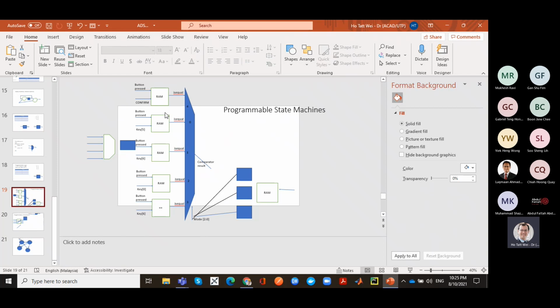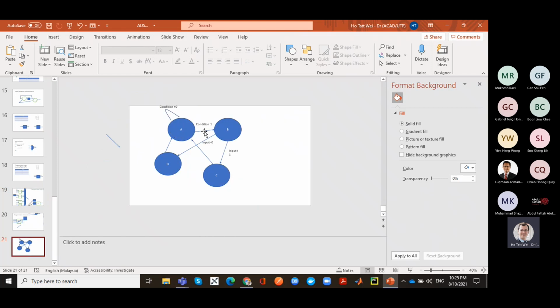It might not even complete in two. So if you draw a state transition diagram without a condition for going forward, it's like you haven't even finished your multiplication and you want to do the next operation, the addition. So I encourage you to think about state transitions such that the default is: if the condition for completing the calculation in that mode is not done, that condition is set to 0 and you still remain in that mode.